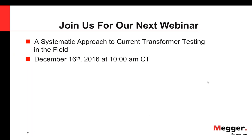Does there appear to be growing power quality concerns with more power electronics being used in facilities? Yes, absolutely. As more equipment is being used, you're adding more nonlinear loads, so you're getting more distortions in there. As those distortions increase, especially as their frequency increases, because of the higher switching rates now, you're getting higher frequency harmonics. You'll hear people talk about looking at harmonics that are extremely high. Really what we're looking at is between the 35th and the 45th. We actually go up to the 128th, but I've very rarely seen anything up that high.